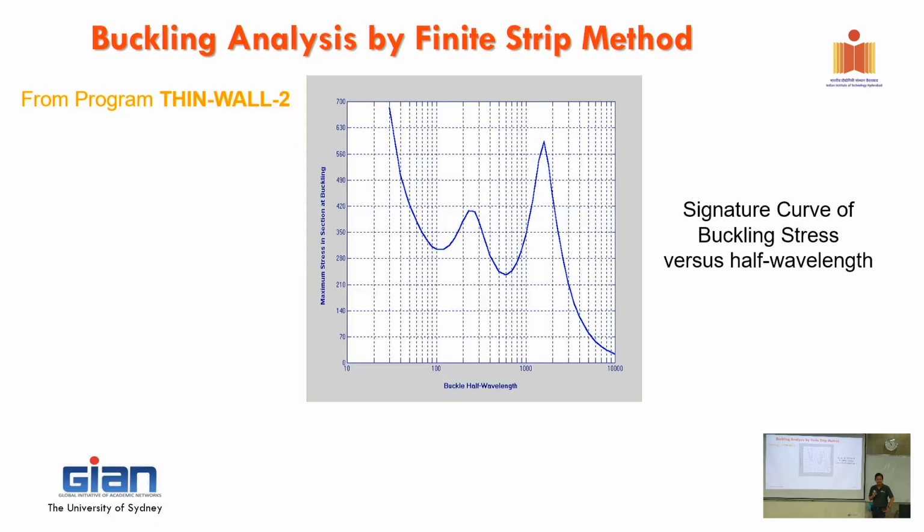First, a very good thing is they give you the properties of the section, the mechanical properties. So what you do, you just input the cross section, whatever section you think about, and you press the material property. It gives you everything. Ix and Iy, it gives you the Zx, Ze, Zy, that's what we learned last time.